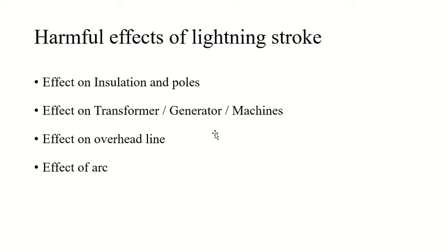You understand how dangerous it can be, and that too in only 1 microsecond, and decay to the half peak value in about 5 microseconds. So it is a very transient process, it happens very quickly, but too much voltage and it will destroy your system. Such a steep fronted voltage wave will initially travel along the line in both directions, with the velocity depending upon the value of the capacitors and inductors of your transmission line or distribution line, in short.